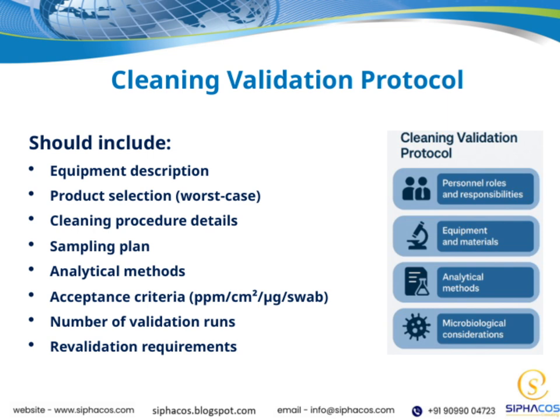Acceptance criteria set the threshold for cleanliness. These are the maximum allowable residue levels, and they need to be clearly defined to determine if cleaning is successful. Regarding validation runs, we typically perform multiple iterations, say at least 3, to demonstrate consistency and reproducibility of the cleaning process.